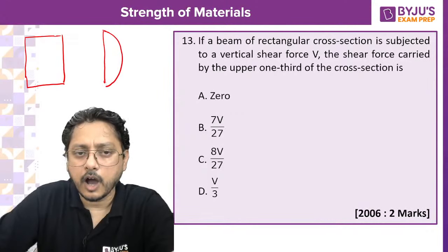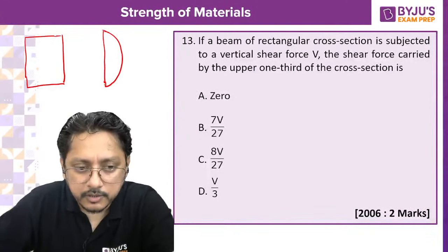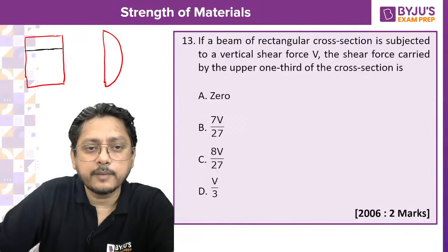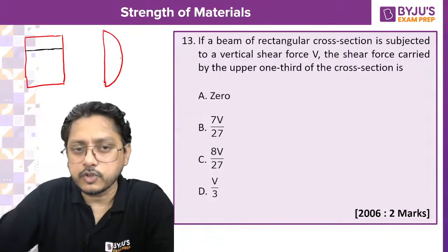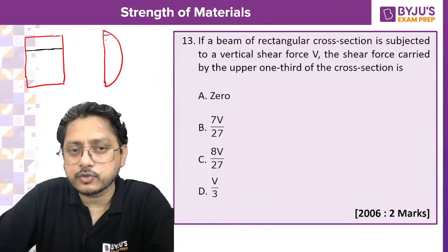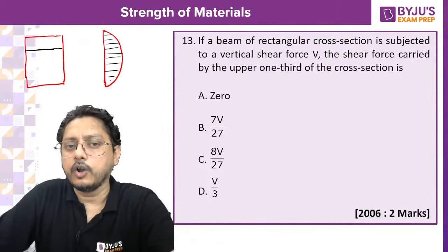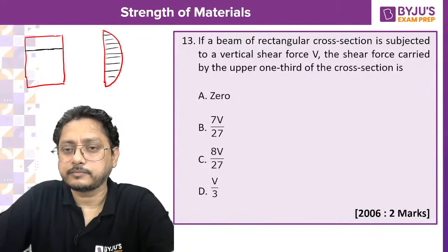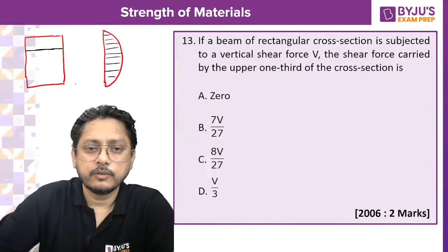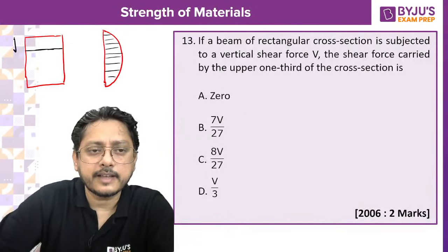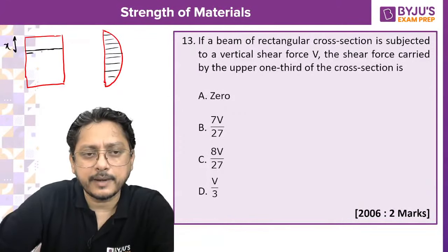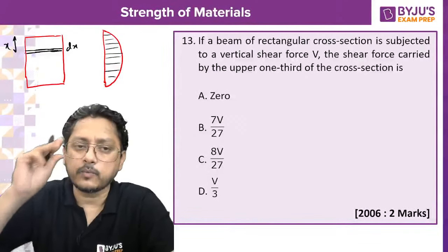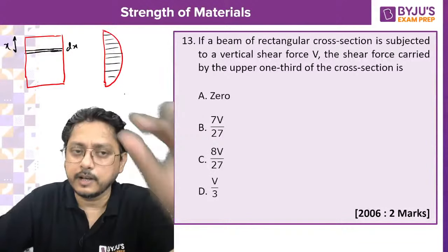Now he is asking how much force will be carried by the top 1/3 portion. But first of all, we know that the shear stress is varying all over the depth. So how will you calculate? Take some x height from the top, and take some dx element, find out the shear stress here, and the total force created by that very thin element dx.